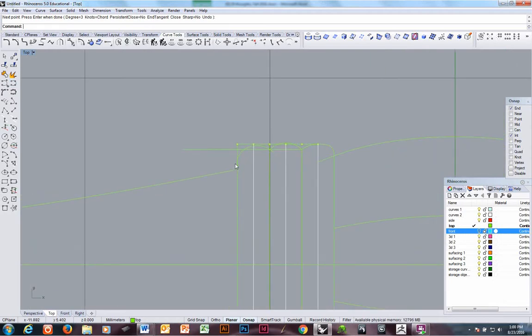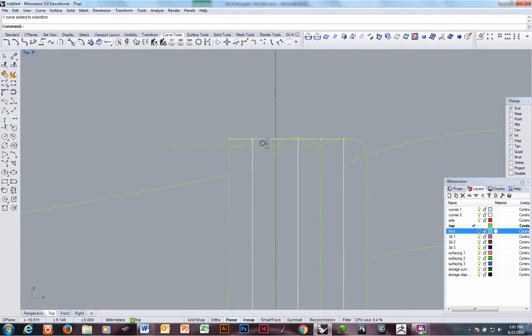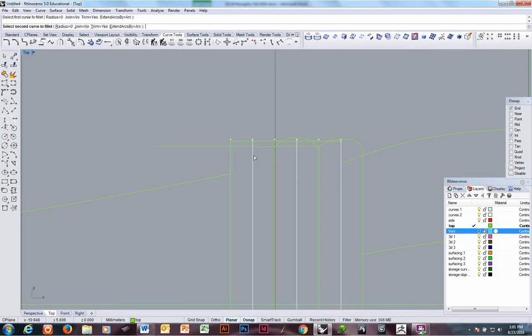I really want to chop off some of this height right through here. I think I can. I think I can get away with it. Okay. So to do that, I'm going to lower this down a little bit. Fillet it. Gonna split this so I can do a blend curve like I did with the innermost flute.